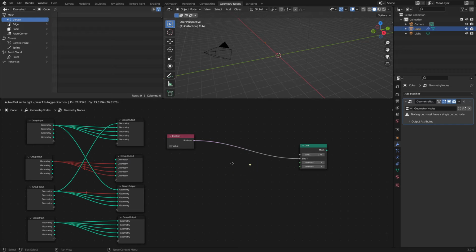Now you see I've kind of got this little dot following me around. I'm just going to drop it right here. This is a reroute node. I'm going to grab my output here, stick it to the reroute, and now I can reroute from there a few times like that. Okay, that's your reroute node.